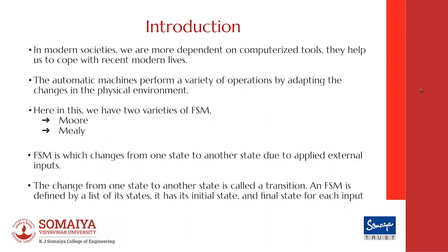Here we have two varieties of FSM, that are Moore and Mealy. Before getting started with Moore and Mealy, let's understand what an FSM is and how it works. An FSM changes from one state to another due to applied external inputs. The change from one state to another is called a transition, and an FSM is defined by a list of its states. It has its initial state and final state for each input.